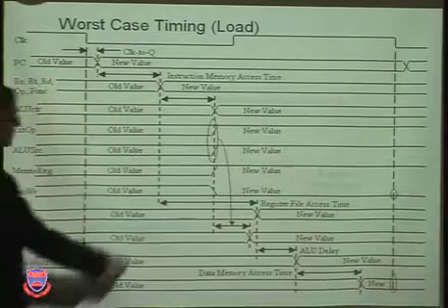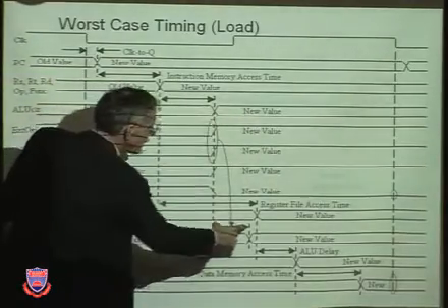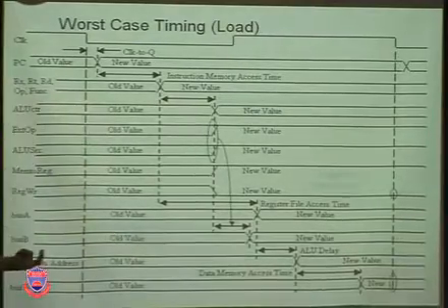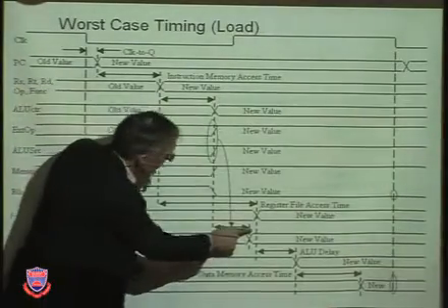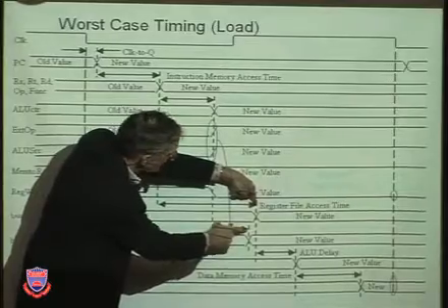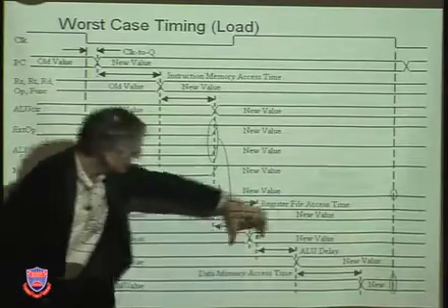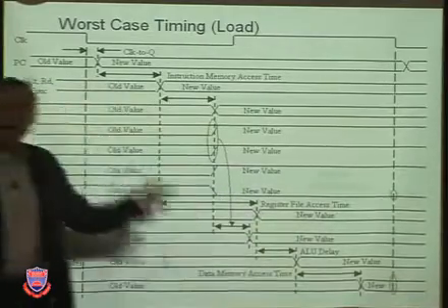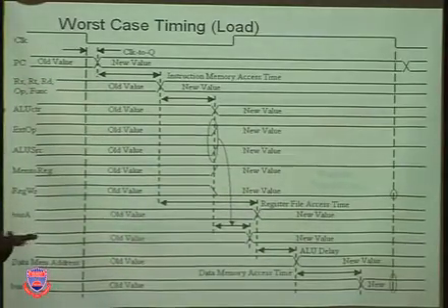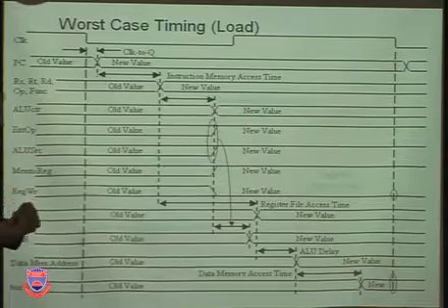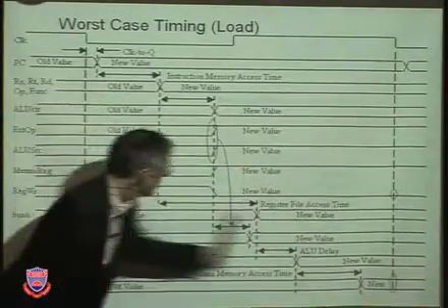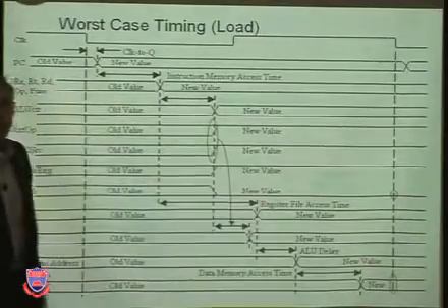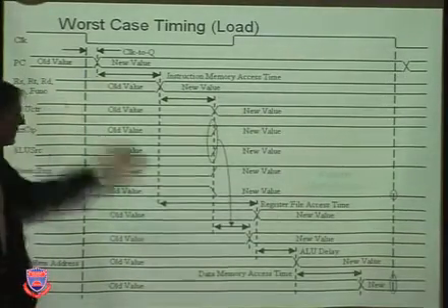In addition to that, as you can see here, from this point here we're also having a slight delay for the delay through the extender and the MUX for the immediate field. So the immediate field shows up, as you can see here, sooner than the RS field. And now we can add them together in the ALU. But the ALU delay is not zero either. So now we have an ALU delay to add the sum of those two together. What does that produce? It makes our address. Now we have the memory address. Wow. From here all the way here just to create the memory address. Well, you can see why. There's a set of sequential combinational delays here in sequence, R to R to.